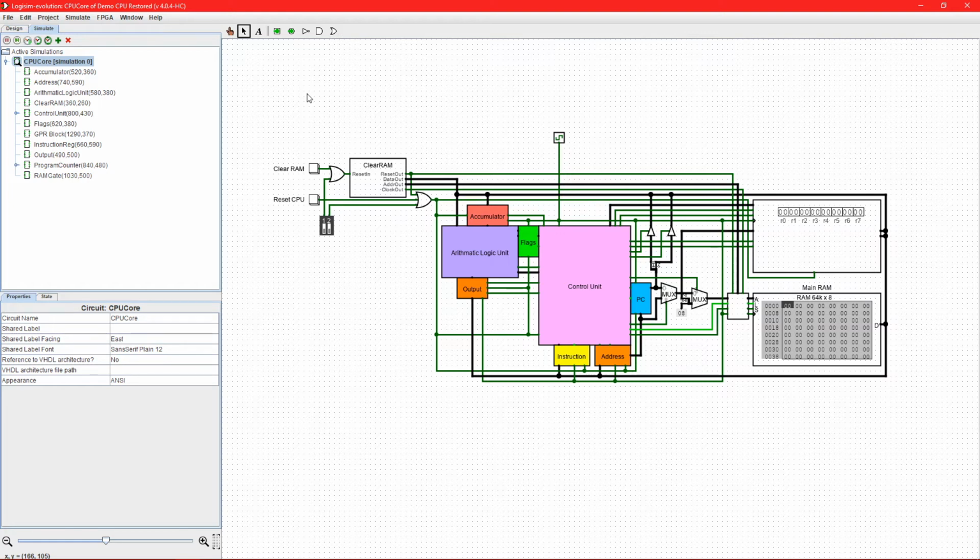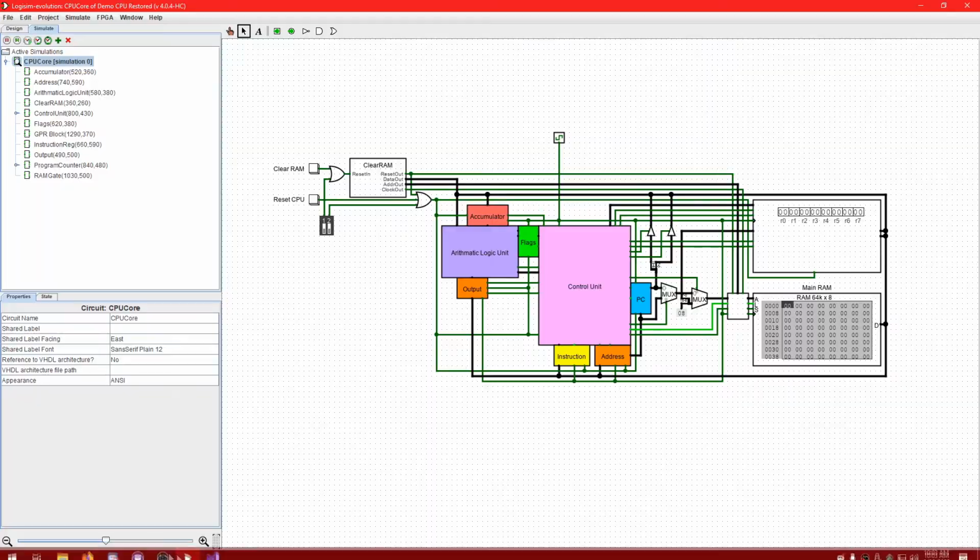But that was quite a bit beyond my skill level, so what I did, because I had no choice, is I set it aside and decided to enhance the demo CPU to get a bit more experience with the basics before going into more advanced stuff like instruction pipelining. So there are a few instructions left that I need to implement. By the way, I cut out the part of me implementing the rest of the microcode. The processor does not yet have the hardware to process some instructions, so I just left out the microcode for those instructions altogether. Anyways, now it's time to load the microcode into the ROMs.